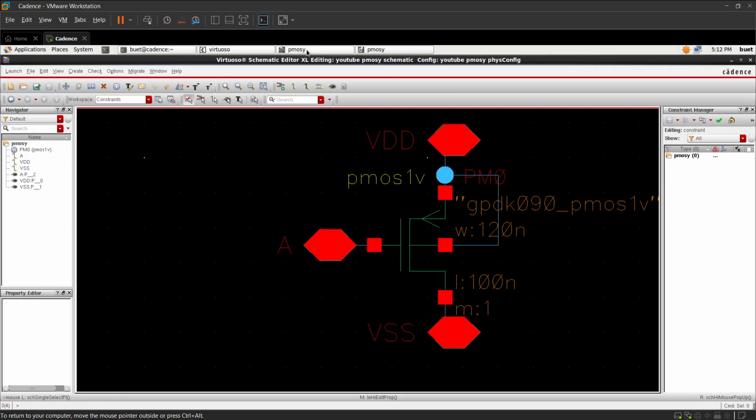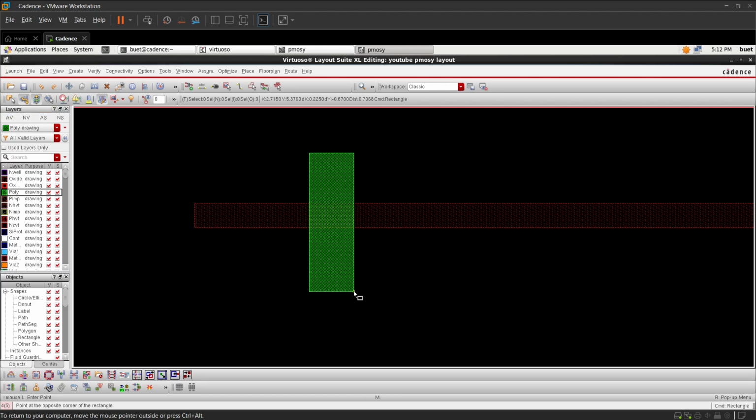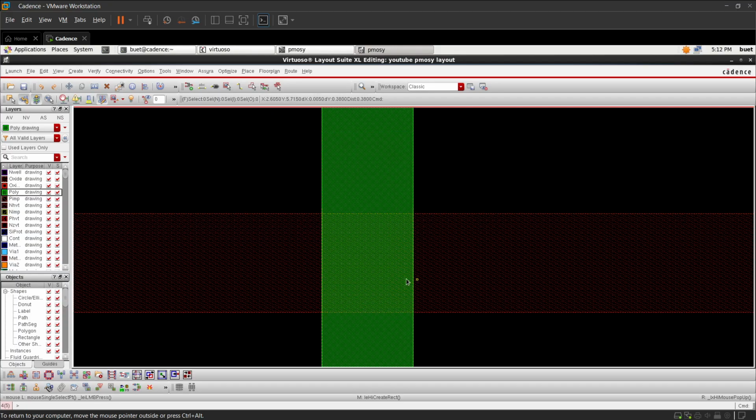Okay. Next thing you are supposed to do is our gate. Okay, poly layer. Poly layer helps in the formation of the gate. Next, go to the search bar, select poly over here, press R, go to layer, and we'll be getting poly over here. This is going to act as our length.